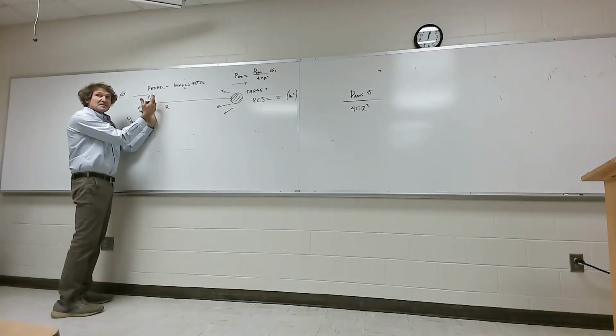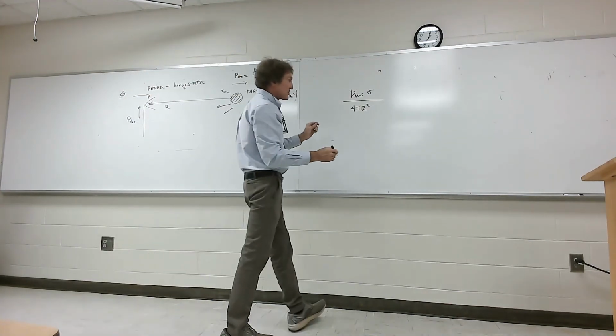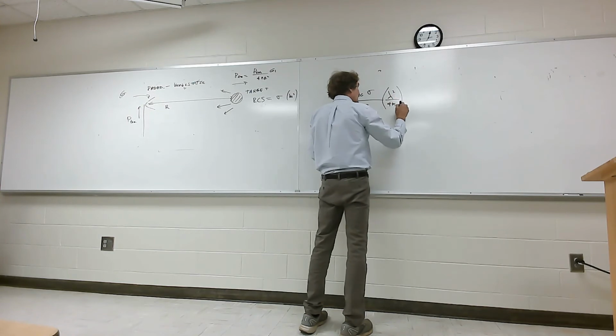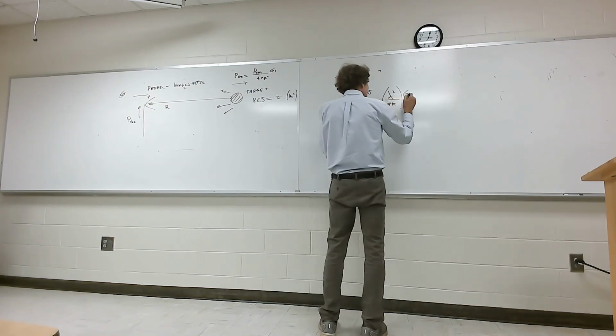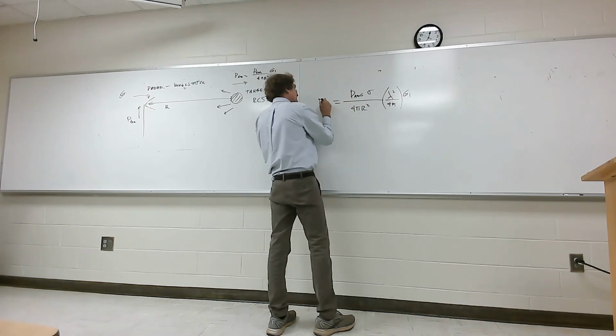And when it collides with this antenna, which has a certain electrical size called the aperture, that's how much power is received. So when I take this right here, and I'll clean this up for you in a second, I multiply it by the aperture, which is lambda squared over 4 pi, times the gain of the first antenna. That's the electrical size, and this would be P received.